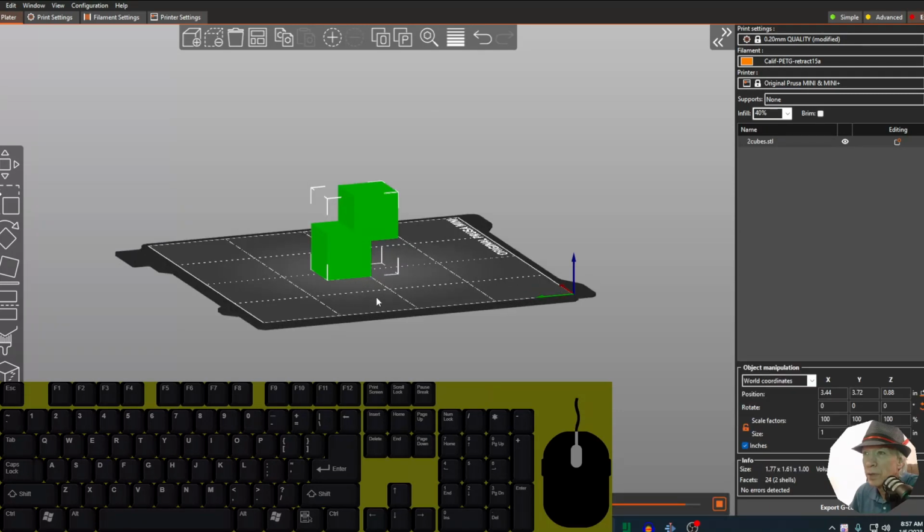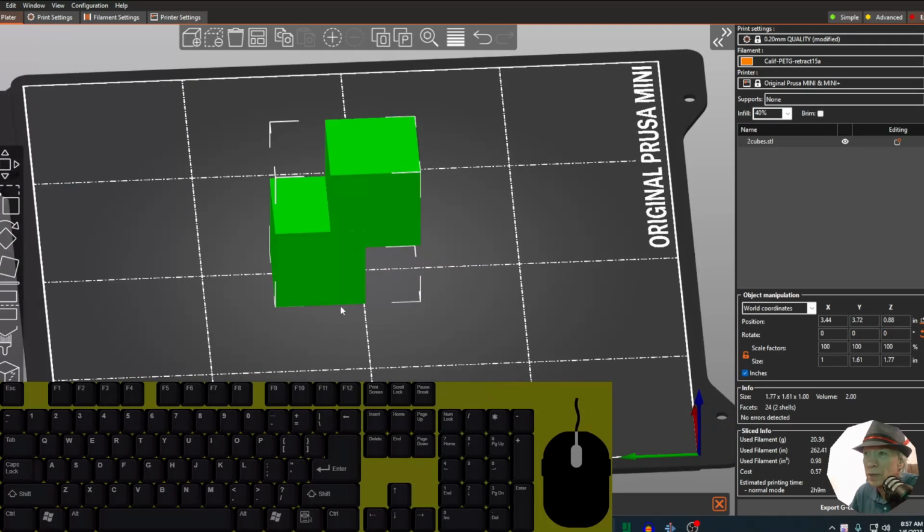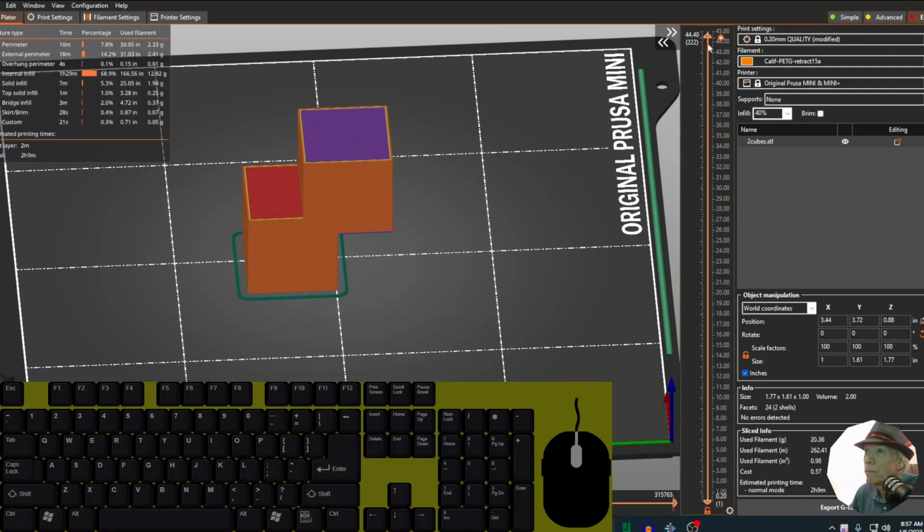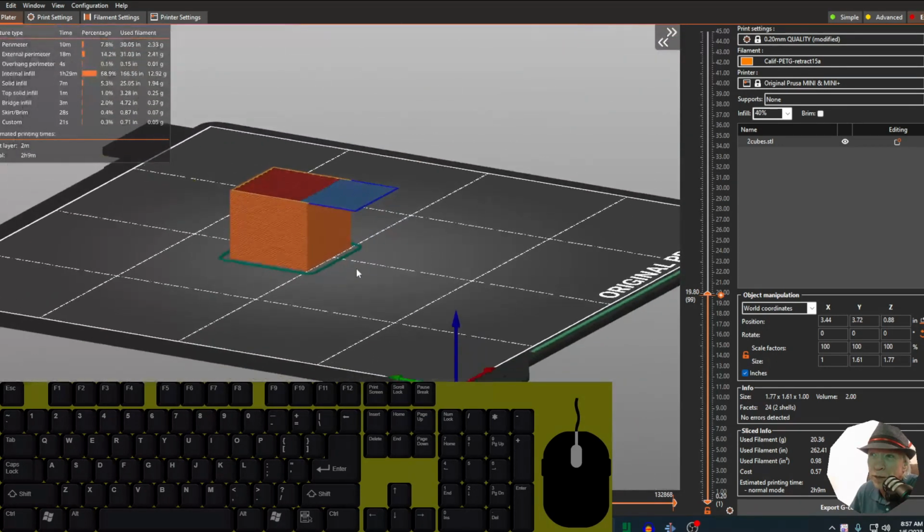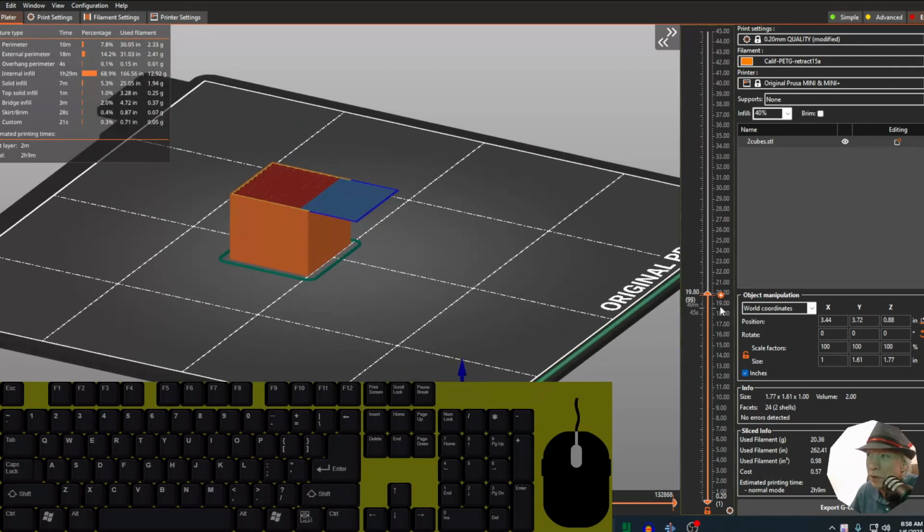That would kind of be impossible, because as you printed these layers, right there, this is not going to keep the hot plastic from falling down on the bed, and this is just going to turn into melted plastic that falls on the bed and just mush, and you're not going to get the shape you think you're going to get.